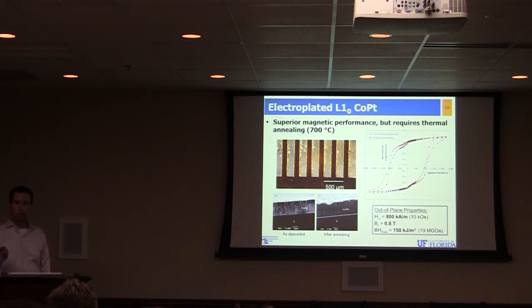And quick question over here. If you're going to talk about it later, great, but how does this compare to the bulk properties of the material? So if you took the same material and just made a magnet that's a centimeter by this alloy? Yeah, this is pretty close. I think the bulk properties for this is like 225 for BH max, if I remember right. It's close. It's not quite there. Part of that's because we have some cobalt dilution here. This was about 10% cobalt.